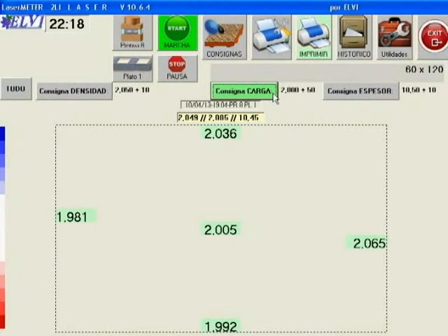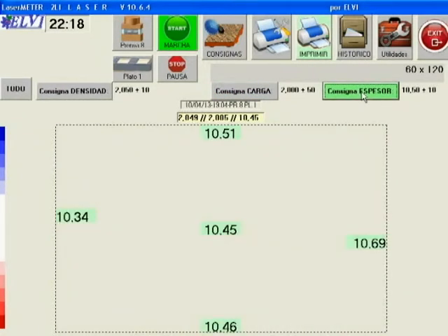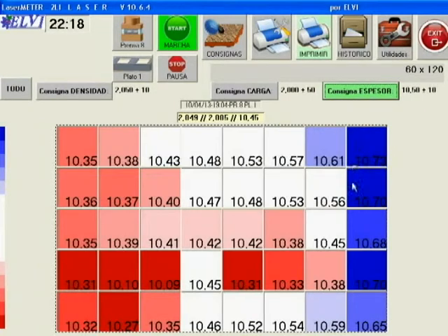According to the distribution of load of clay, we can deduce that material has moved to one side during pressing, producing areas with lower thickness, or one side with greater thickness. According to the numerical values, we appreciate that the difference between one side and the other is around 4/10, and in total, we have a difference between the minimum and the maximum of almost 7/10. The cost in polishing would be great. If the material was a gloss, or partial polishing, it would be virtually impossible.